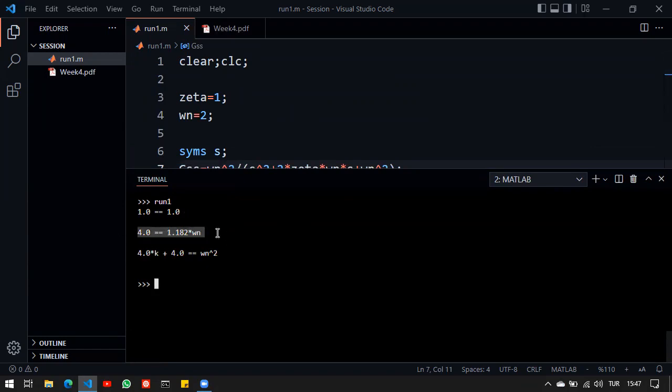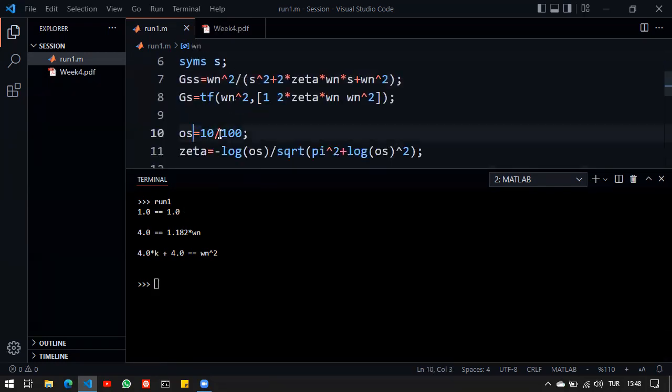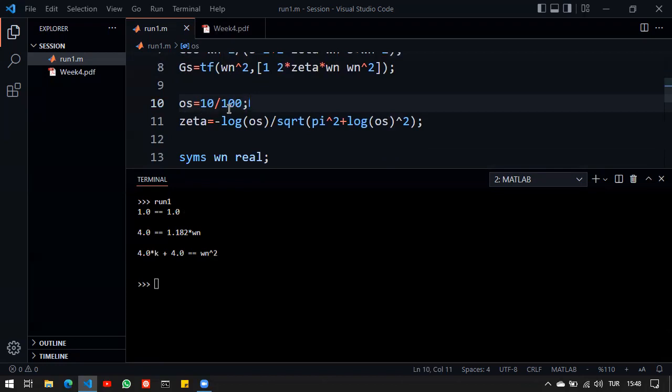Now, if I'm going to calculate omega n from here, what I can do is directly plug it into this equation, and I can conclude what k should be. So this shows me that there is a certain limitation on the system. I can maybe decide on the overshoot value, because I can change this here. And that would give me zeta, and I'm going to adjust the value there. But I cannot also change omega n for this system, because my coefficient only affects the constant term. So therefore, the S term here, for example, should be restricted to the system coefficients or this equation here.